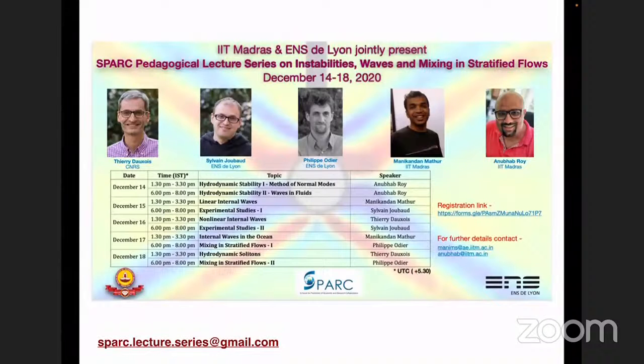If we had used a Blasius profile also, would we have gotten this? You would have obtained it nonetheless in that case also. The growth rates would differ. The thing that is required is that the gravity waves which would have propagated on the interface if there was no flow, their speed needs to match the shear flow at some height. At that location, the vorticity gradient should be non-zero. The vorticity gradient is proportional to the second derivative of the shear flow. So you see, it's a very general criterion for the instability to be there. Now, what growth rates you find will depend on the exact flow profile you take.